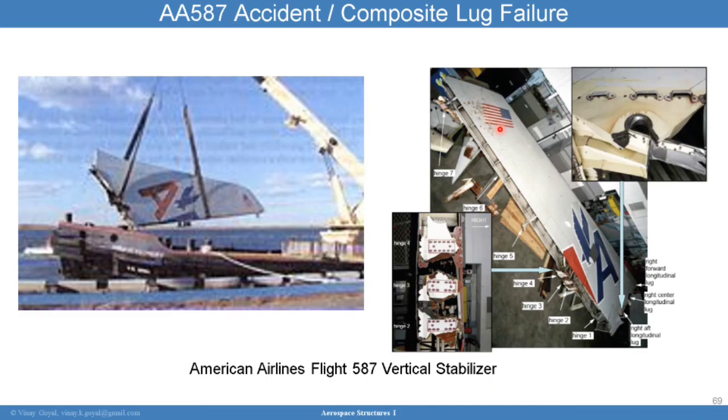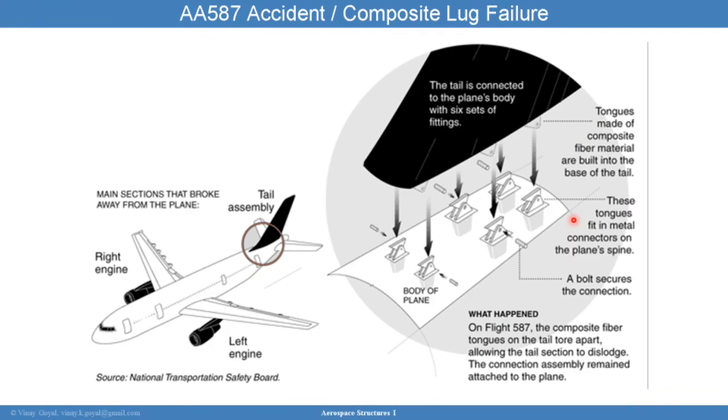There are things that need to be kept in mind, which is that the designers did allow for these inputs to occur. And so in some ways one could argue that the design allowed for pilot inputs that should not have happened in the first place. So yes, there was corrective action on how to approach this in the future, but there is also concern about this vertical stabilizer. Now, the vertical stabilizer is connected.